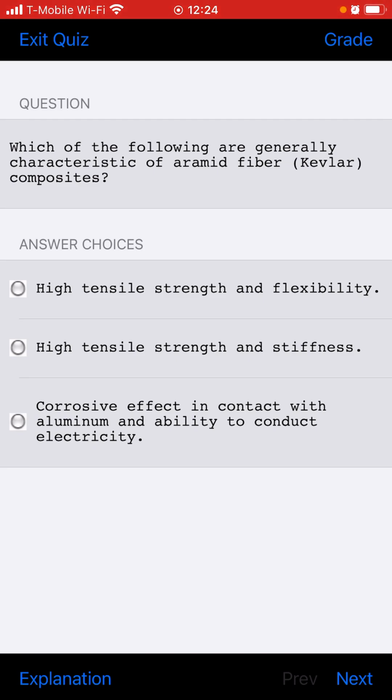I don't know what they're talking about, so let's look at the explanation. For the greatest strength in a bent piece of material, the layout should always be made so that the bend is perpendicular to the grain of the sheet metal.